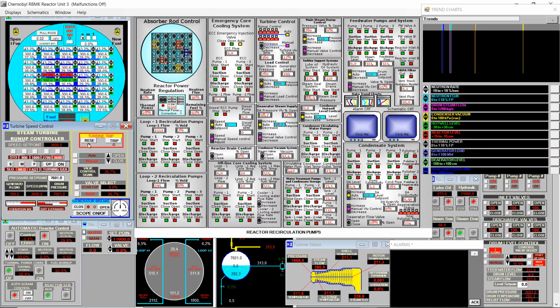Now I just set the turbine into manual mode with an aperture of the main valve of 26.7, and this is slowly increasing the drum pressure. So now to start reducing power, I will switch back to auto,